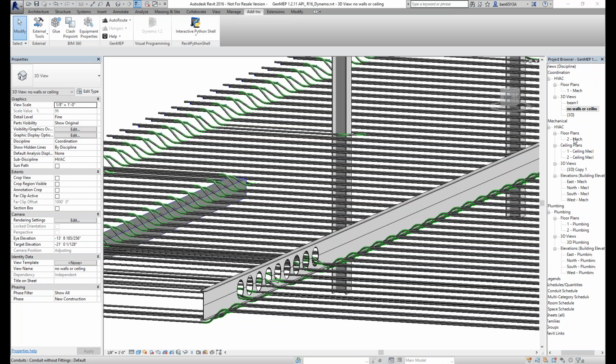The way that we would do that right now is that we would put in an intermediate point that was offset from the component. So you'd have it hit a waypoint before it did the rest of the route. Within Dynamo, though, you could come up with a script routine that would do that logic for you.